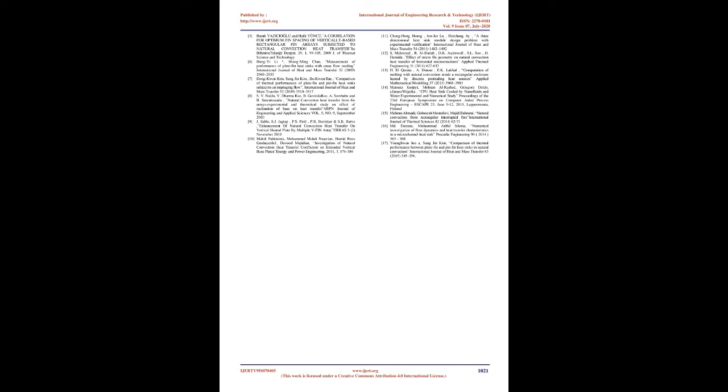7. Results and discussion. Conjugate heat transfer simulation work consists of analysis of both convection heat transfer and conduction heat transfer processes. The air, the fluid, flows over the fins at the interface regions of both solid and fluid. The main equations solved for fluid flow are the momentum equations and turbulence modeling equations. Solution of these Navier-Stokes equations gives the velocity vectors and temperature in the fluid flow region. The energy equation is solved for both fluid (convection heat transfer) and solid (conduction heat transfer) regions to obtain temperature distribution along the length of the fin by applying the interface boundary conditions at the coupled region.